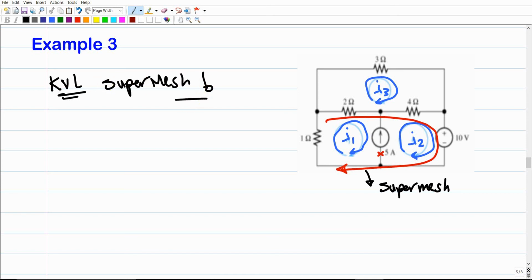as given here. So what we're going to end up with here: how much is the voltage over this one? It will be 1 ohm times the current over this resistance. The current over this resistance should be I1. The current over this resistance should be the difference between I1 and I3, because I3 is going to affect here, right? Let us draw very quickly the currents over all of these elements. There should be I1 going in this direction, and there is I3 going in the opposite direction. This is what should be over the 2 ohms.